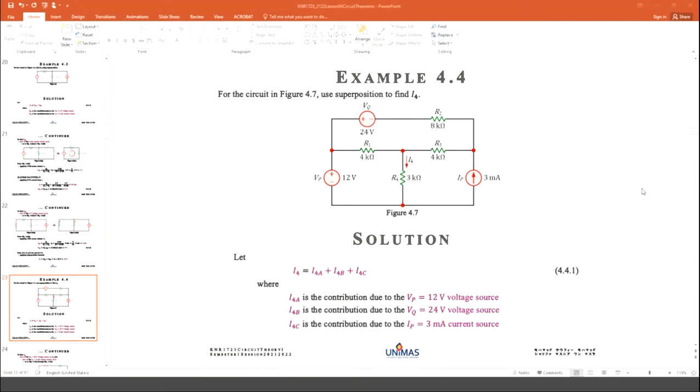Right. Okay, IP, what do you do? Open circuit. So basically, if it is open circuit, what happened to this wire? Gone. Right. So with that, what happened to R2 and R3? They are in series now because they can be connected. Okay, good. You do not need to explain, you just see it. So this is technical.